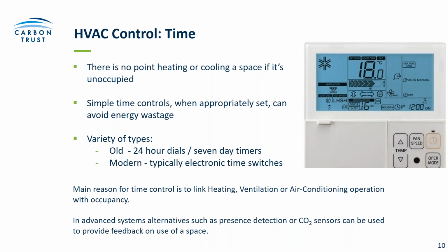Whenever it comes to areas like meeting rooms, good use of presence detection can be made through PIRs, potentially just switching off air conditioning systems for individual rooms when there's nobody there, and that gives that flexibility with regard to the use of the space.